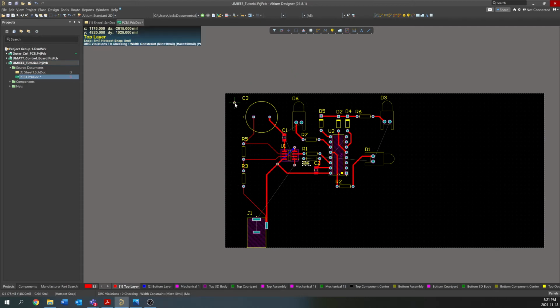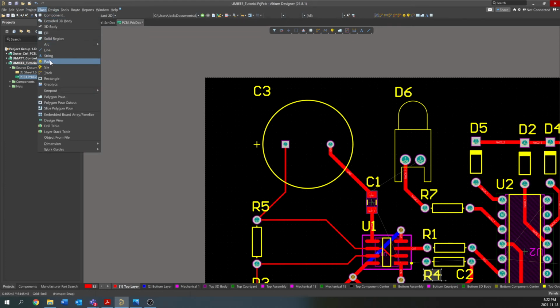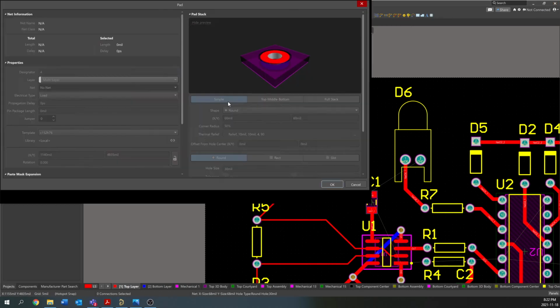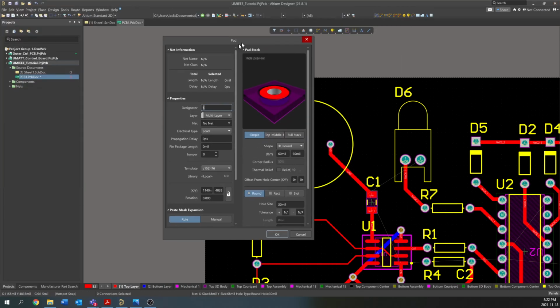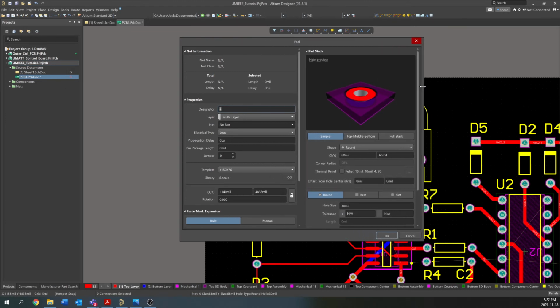You can either use vias for mounting holes, or you can use through hole bodies for mounting holes. One way to do that is to go into place here, place pad, and we actually get what is essentially the same as one of these through holes, and we can click that, and this is the pad, change size,